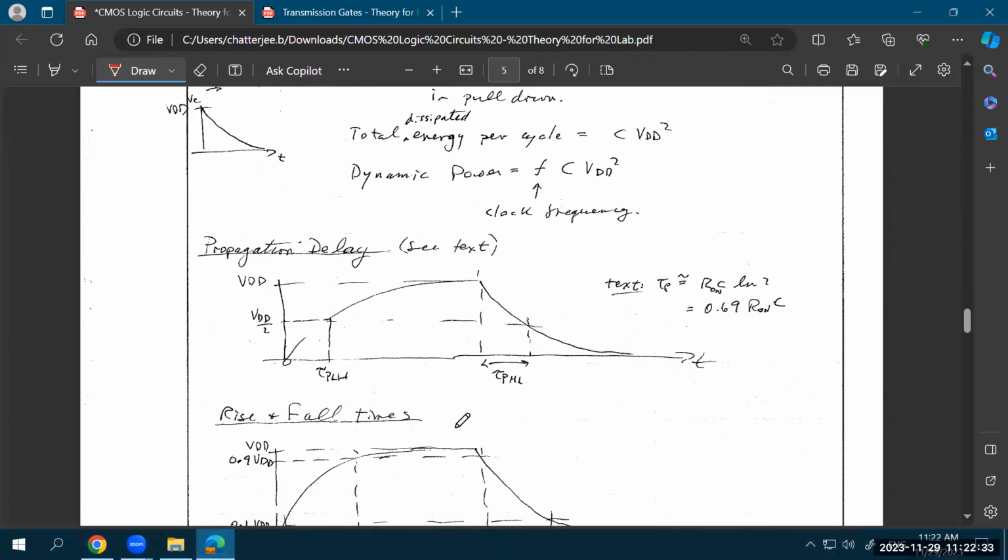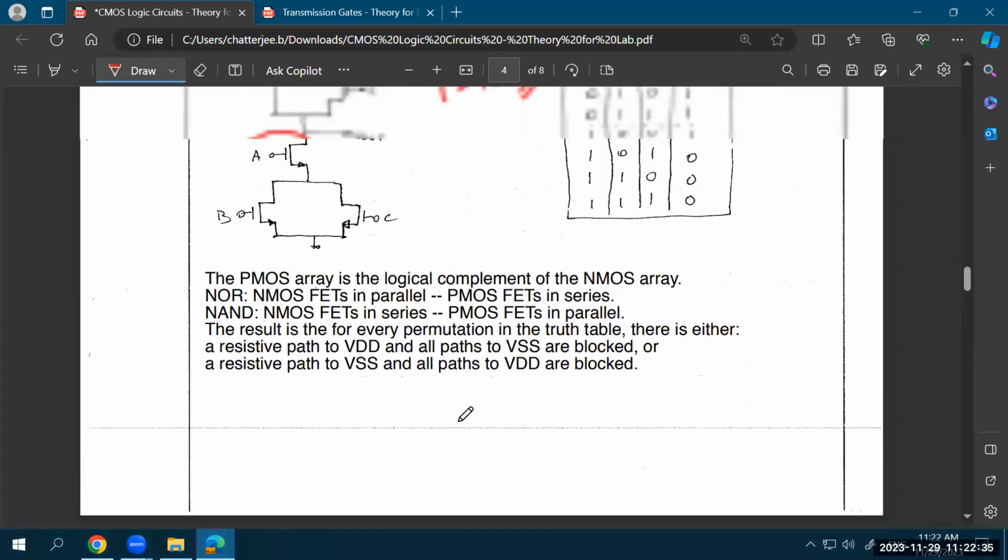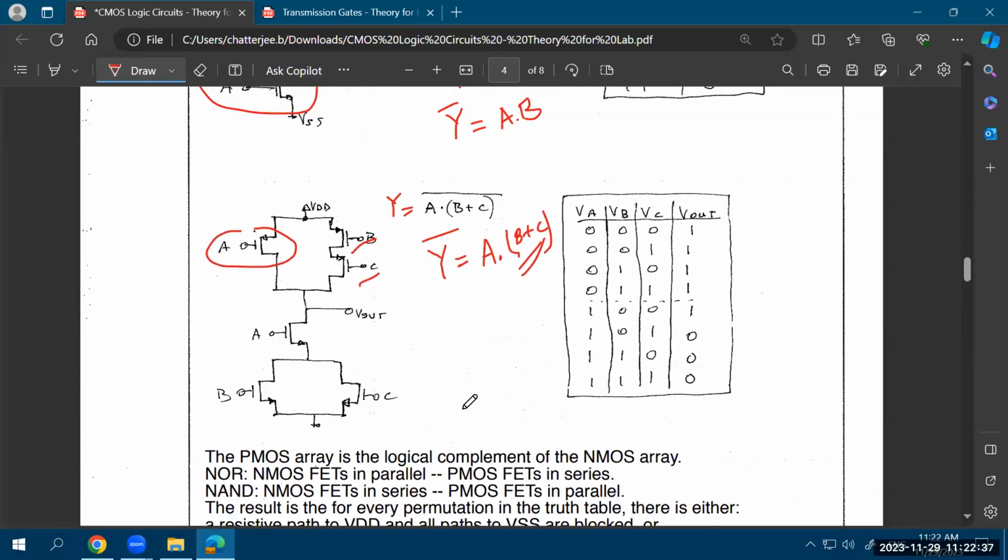So what we discussed till now is short-circuited switch and open-circuited switch. In the real world, an open circuit is not fully open circuit. It's not infinite resistance. There would still be some finite resistance, and that's the reason why in the real world you'll see some amount of leakage through the devices.